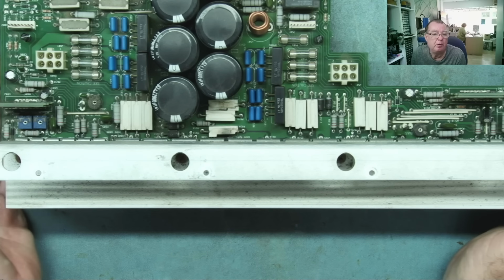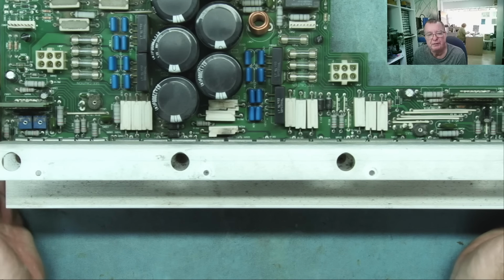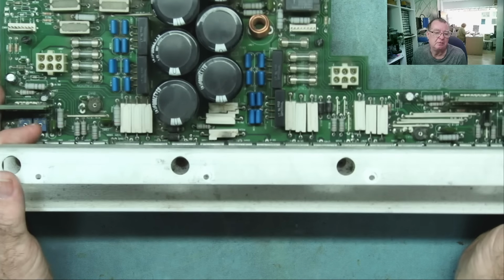Another good example would be, quite often, triacs. These are effectively mains switches, and they're driving things like heater elements and such like, okay? If the heater element fails, then the device will fail. We have power devices driving motors. If the motor seizes or something goes wrong with the equipment and the motor jams or something mechanical happens, or maybe the motor wiring is just burnt out, then that will cause the driver devices to fail.